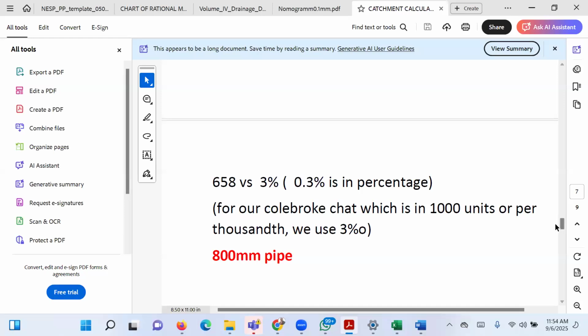So those Jigawa people, something they need to work on is to use bigger pipe sizes. So two impacts is that they will end up using big pipe sizes, which will impact their cost, and then they might have to dig in some cases, or the pipe needs to flow on the surface in some cases. So that's the implication of having a flat land.